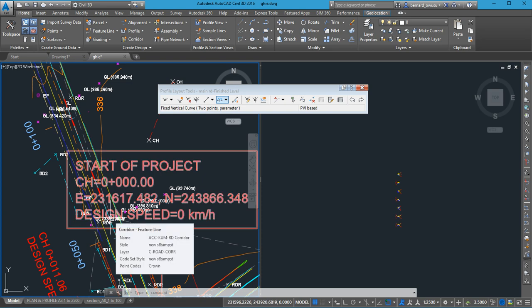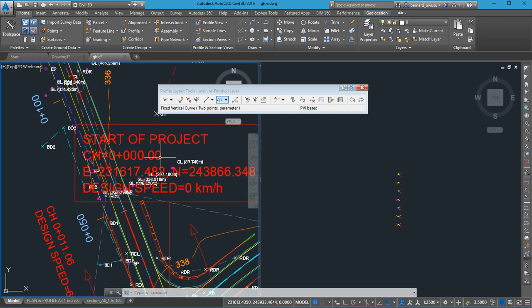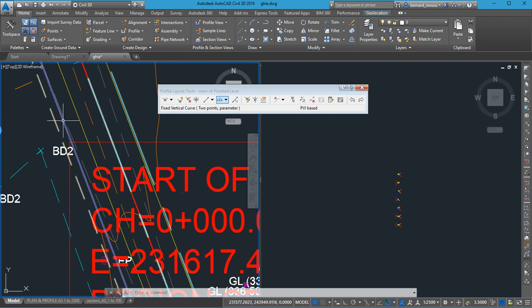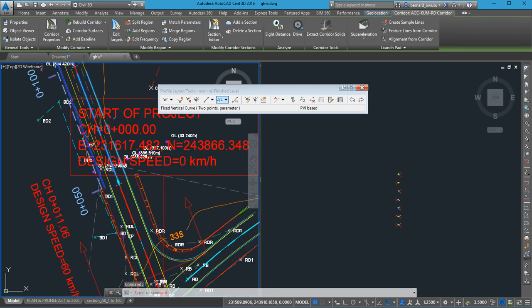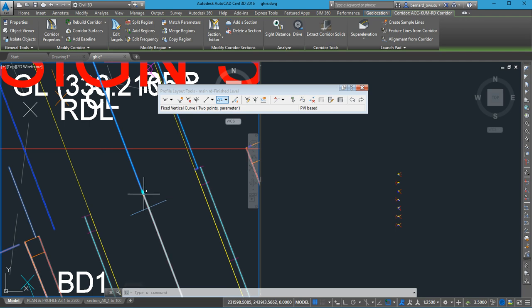Successful. Yeah. I started from the... Because I told you to change the start. You do not change, but at least you have it. Even if you have it wrong, you can always select the corridor. You can select and change the start point. You see that there's something like a diamond at the beginning. Come and hold it and you can drag it to wherever you want it to start or end.